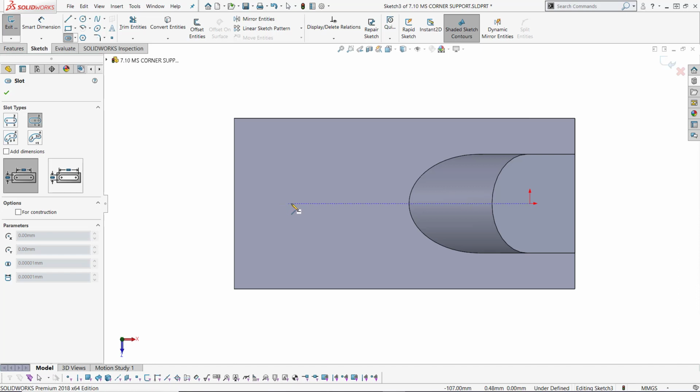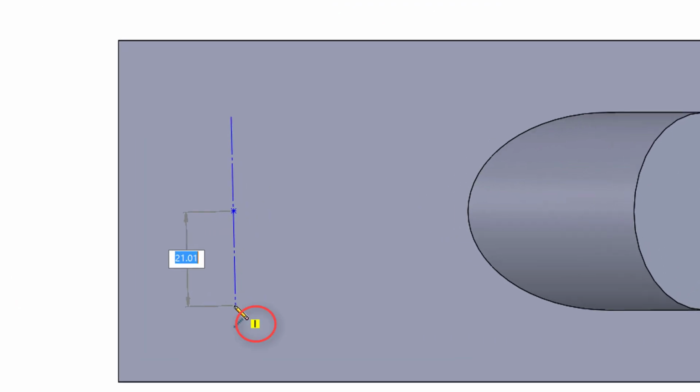So I want this here. Click there, and I'm going to come out. I want this again to be vertical. See how when I snap it down to a vertical, I'm getting a yellow relationship. Now this is the center point. It's going to want to know where the center point is. I will not use that dimension there because it's only a radial dimension. I will want the actual distance between center and center. So I'm going to click that there.